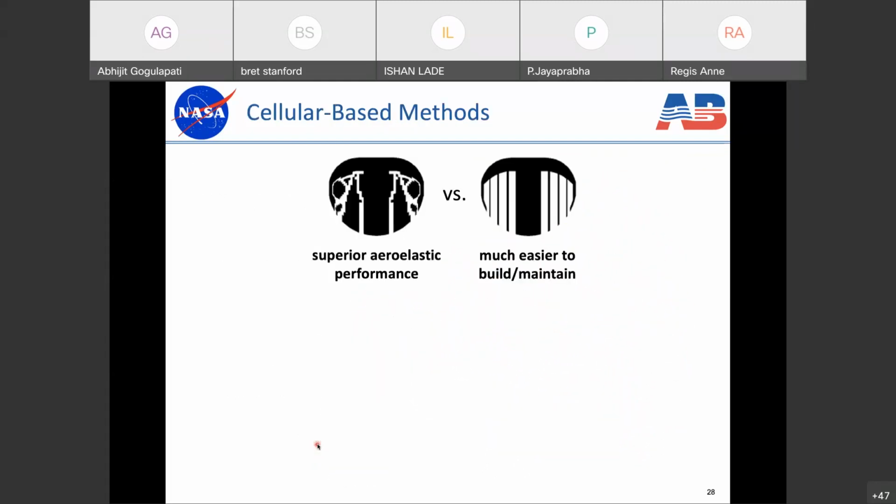Okay, so I want to reach back briefly and talk about these membrane topologies that we got a few minutes ago, for the fixed wing designs. What we were seeing, as I mentioned previously, was that when we did SIMP-based topology optimization for the wings, we continually saw structures with these disconnected two-dimensional islands of carbon fiber floating inside the membrane skin. That's as opposed to a structure that looks like this, where we have a monolithic skeleton structure.